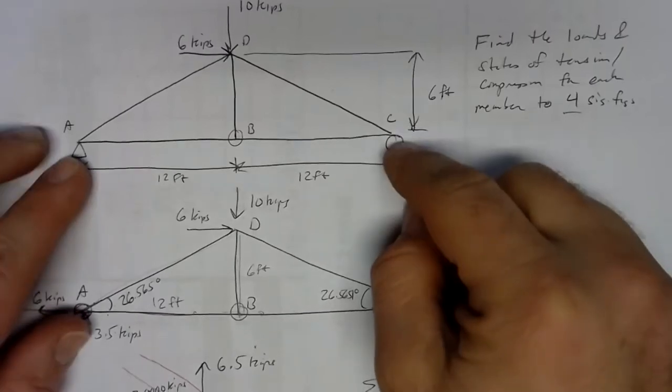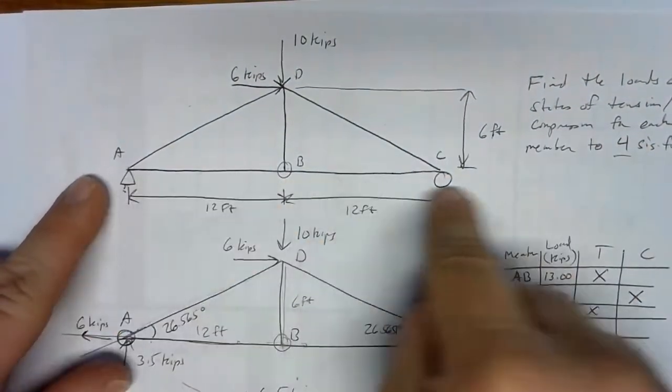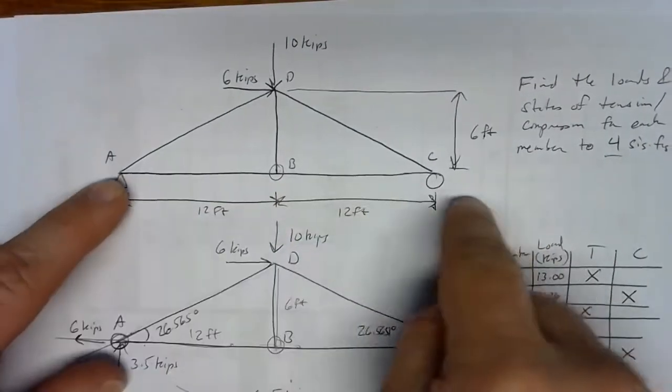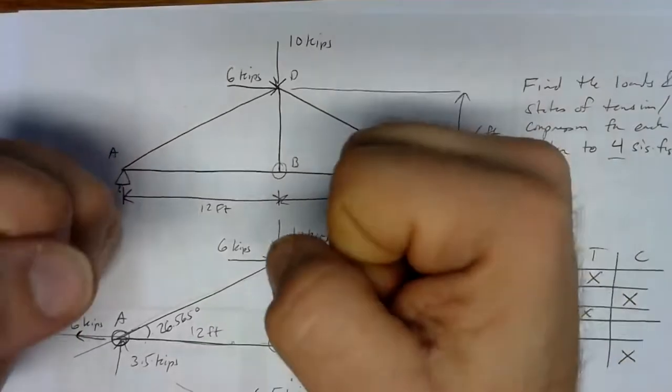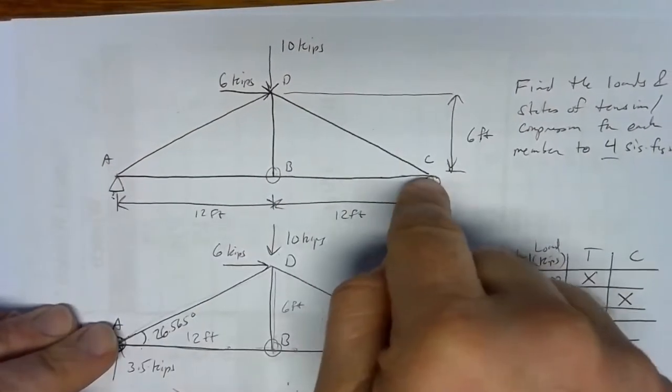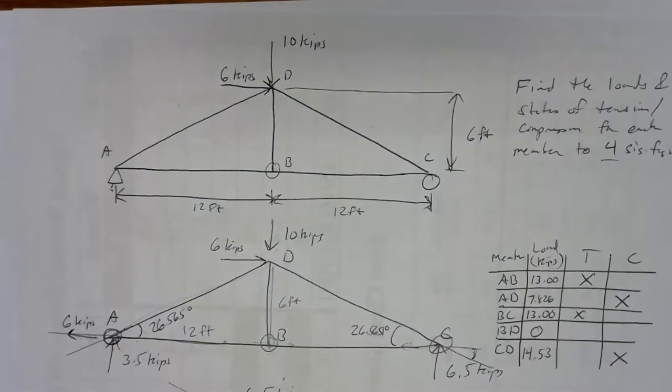And that's exactly what this is trying to do. When you push down at the top, this whole thing's trying to flatten out. Well, the bottom cord of the truss is what's holding against that. And so as the ends are trying to be pushed away from each other, that's pulling on this bottom cord. And that's exactly what happens in a lot of roof structures. The walls are what we're sitting the roof on top of. The joists or the bottom cords of the truss, depending on what your roof structure looks like, that structural element is there to keep the walls from spreading apart.